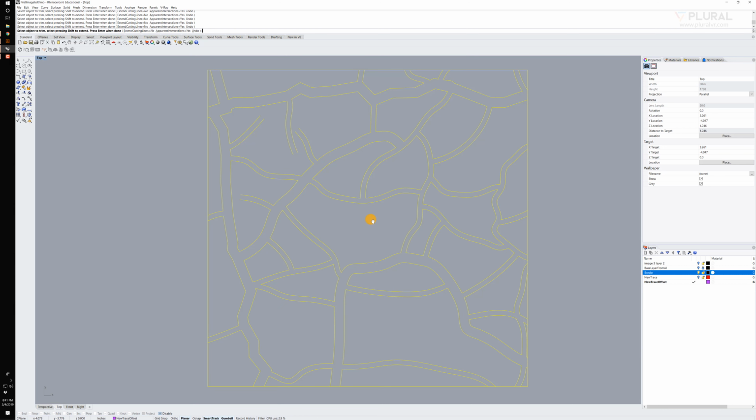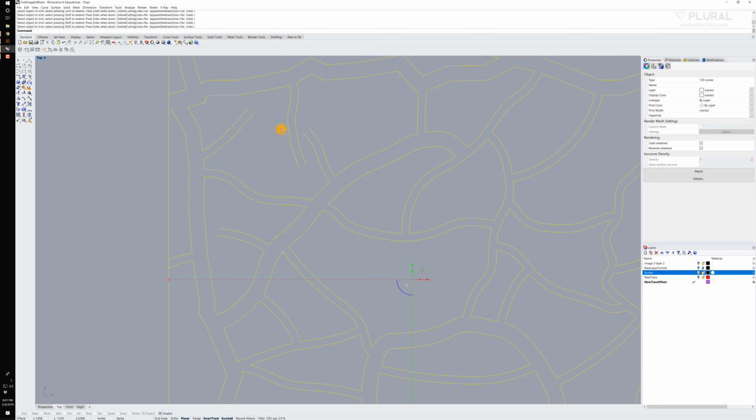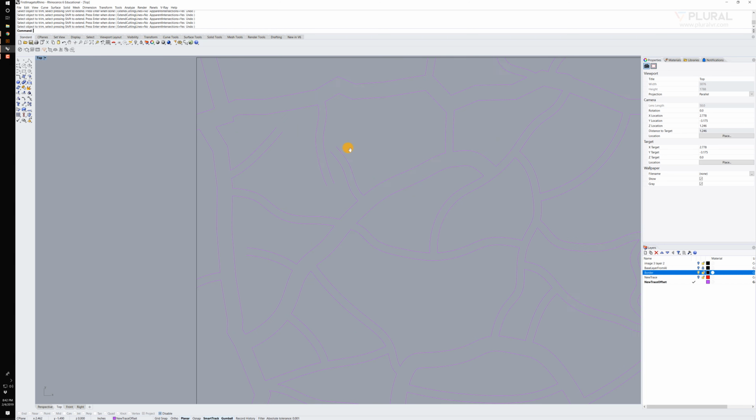All right, so there was all the trimming. You can see there's a few lines here that aren't quite how I want them. I obviously don't want to leave these open-ended. So let's look at the extend command. The extend command is the opposite of trimming. I can set up a border, say these 2 lines here, and extend these lines until they run into it. I could then come back in and use trim and trim that spot out.